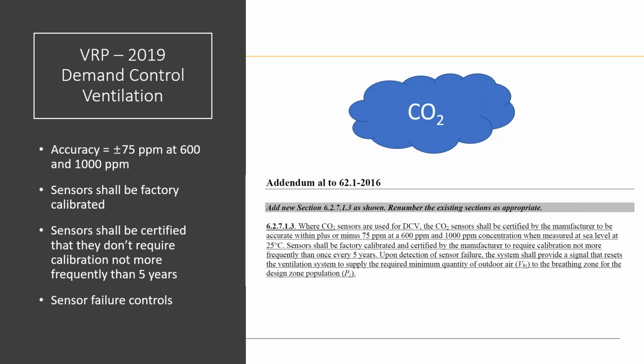And this is something that is not applied correctly in a lot of different applications. You cannot set a limit. If you have 2 people, you put 10 plus 0.06 CFM per square foot divided by all the ventilation efficiency and effectiveness, etc. So demand control ventilation is primarily to help you to decrease outside air during operation, only when it pertains that if you have lower than designed occupancy, and if you know of that change. Is it required? Do you have to use DCV? No, demand control ventilation is totally optional in the standard 62.1.